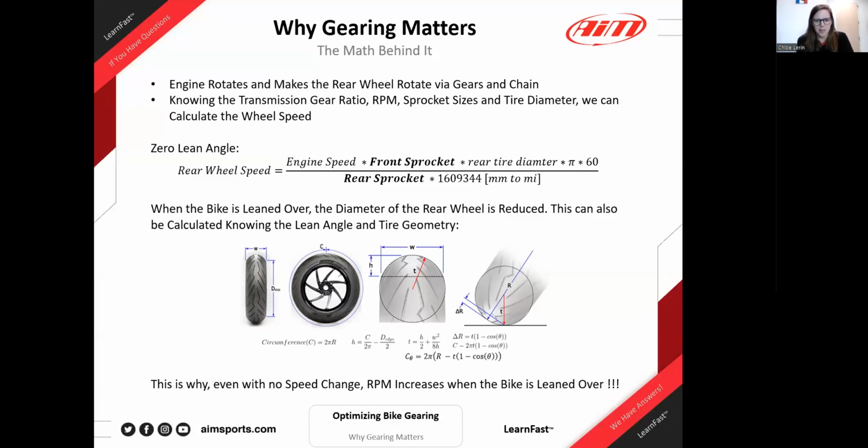You can see I really like this drawing. It's really well done. It gives you the different dimensions of the wheel: the diameter, the width of your tire, and then the circumference. The circumference is really where you start, and that's the distance you're going to travel for one rotation of the wheel, considering that you're not swelling the tire, not slipping, and a bunch of other factors. But we're just talking about theory here. Your tire is perfectly round, it's new, and you're straight up and down. This is the distance you're going to travel.